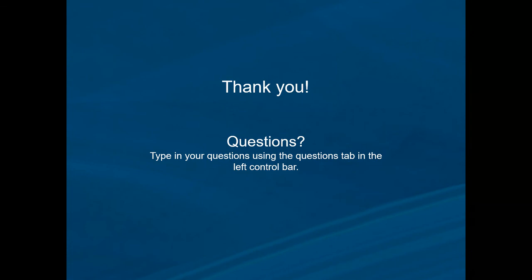Oh, great question. So this is one that we bump up a lot. Typically, those are going to be HEPA filters, and we want to do everything we can to have the humidifier after any kind of high efficiency filter like that. The reason being is that they do such a great job taking everything out of the air that in higher supply condition applications, they actually do take absorbed moisture out of the air.